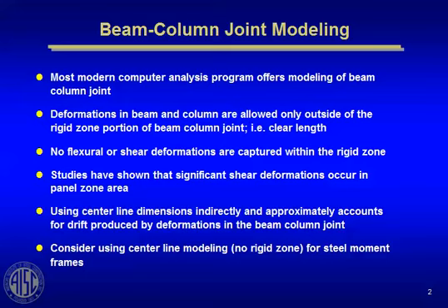If you're doing a tube building like we do in high-rise, where you've got your columns at 10 foot on center around the perimeter or 15 foot on center, there you want to perhaps take a serious reevaluation of how you're going to treat those joints and actually make an attempt to model the panel zone deformation component.